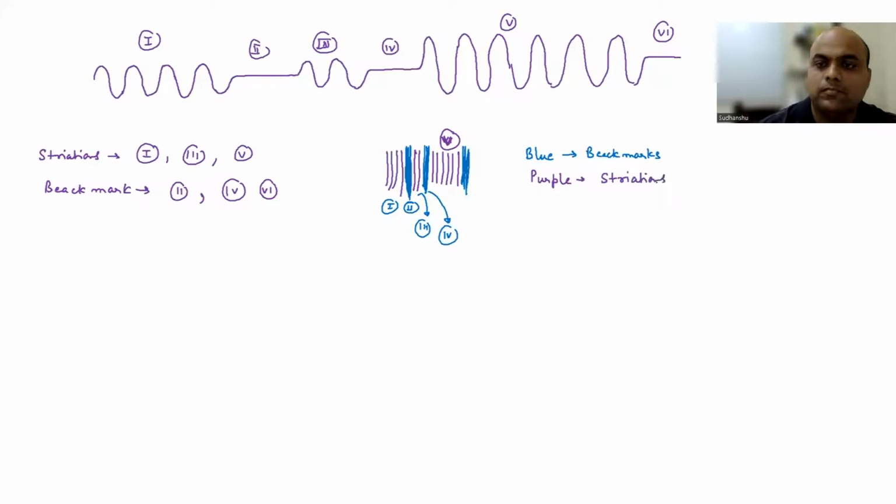Now, if you see, the number of striations is changing between 1, 3, and 5. That you know, because each cycle is going to give you one striation. We discussed that. In fact, if you see the loading amplitude or stress amplitude in 1 and 3, right? Although the number is changing, the gap between striations will remain almost the same because the amplitude is the same, right?